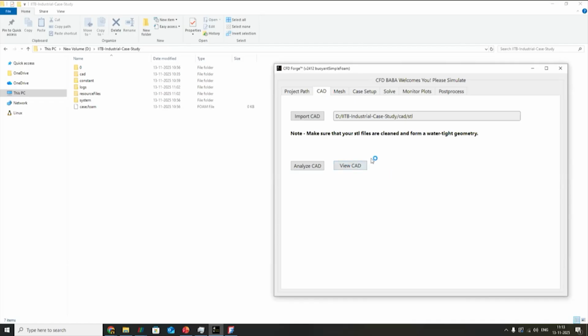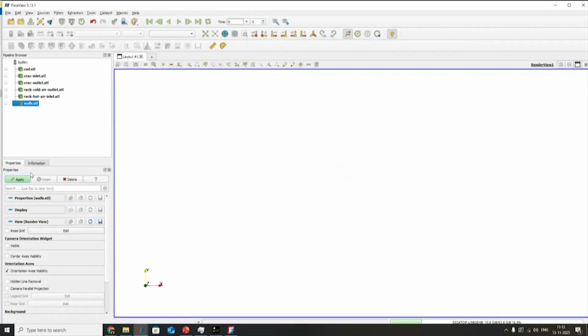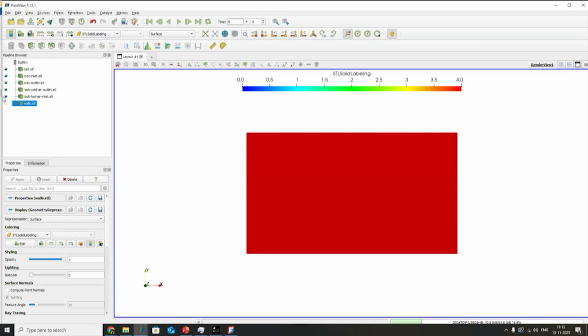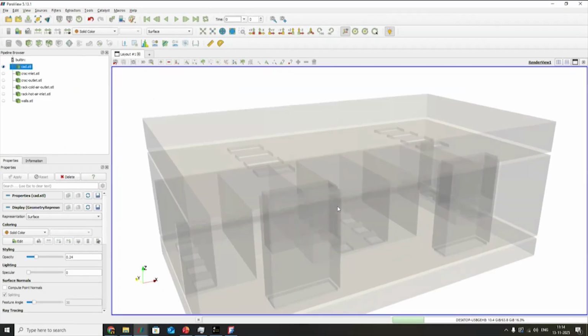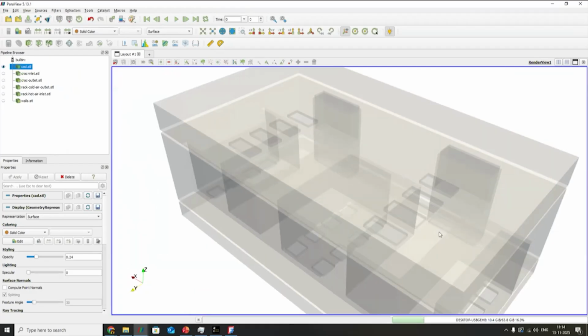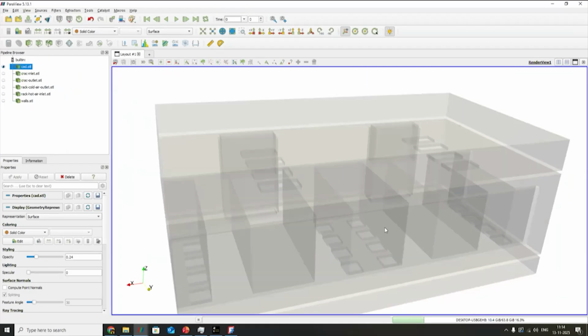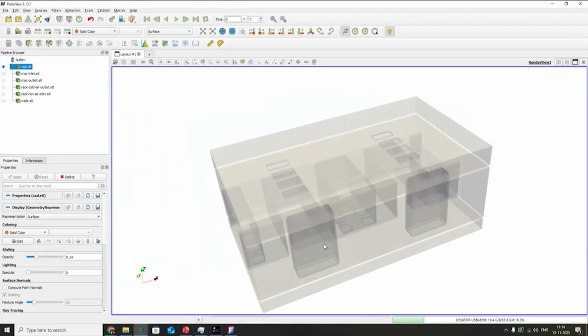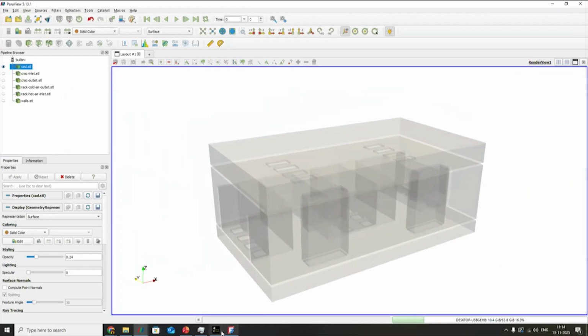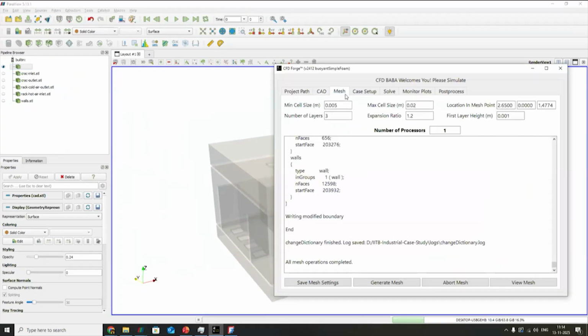And we can view our STL files in ParaView now. Click on apply. Hide all the boundaries and just turn on cad.stl. We can make it solid color, and we can reduce the opacity to view inside and just inspect that everything is fine. I can see that everything is imported correctly from FreeCAD into STL. And now we are ready to do our mesh.